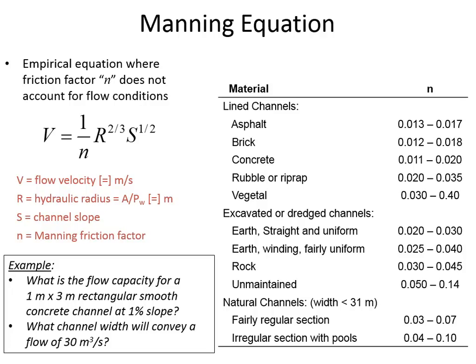And then we've got B times 1 divided by 2 plus B. So 2 plus B is the formula for our hydraulic radius, if we've got 1 meter on this side, 1 meter on this side, and an unknown width of B, and that's to the 2/3 power. And then slope, 0.01 to the 1/2 power.